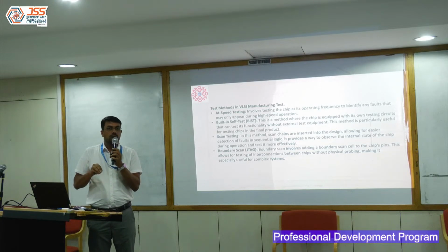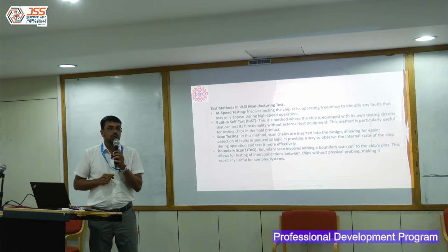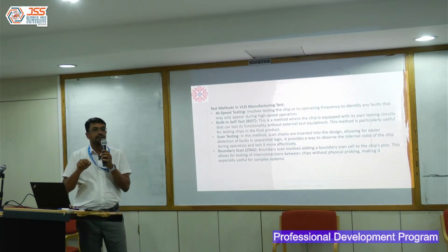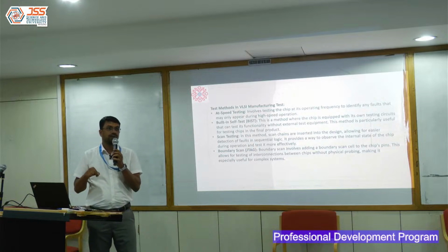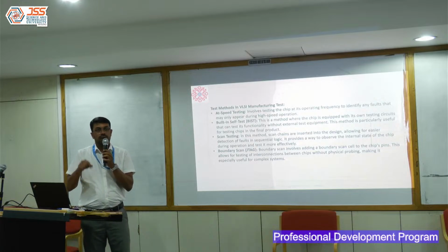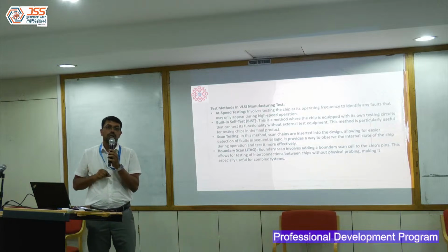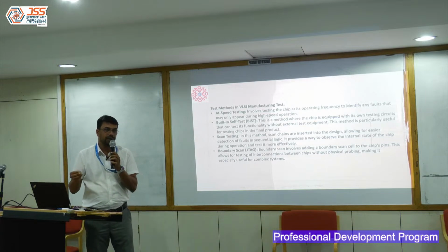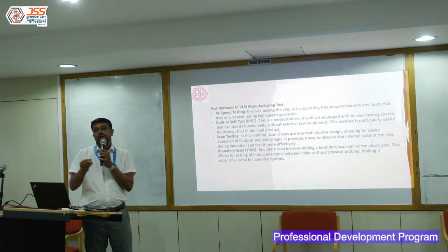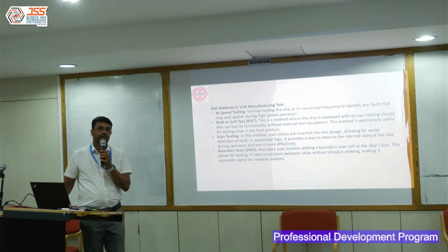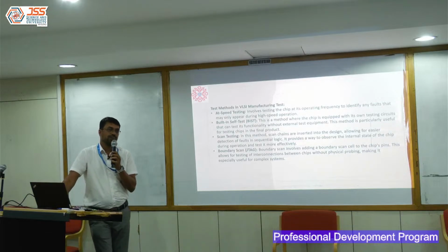With this challenge, how do you feed say 1.5 gigahertz? So that's where we insert an on-chip PLL, phase locked loop. And this PLL will typically require a reference clock. Now that reference clock would be in the order of 312 to 512 megahertz. That frequency you can always apply through a crystal oscillator or any external oscillator source.